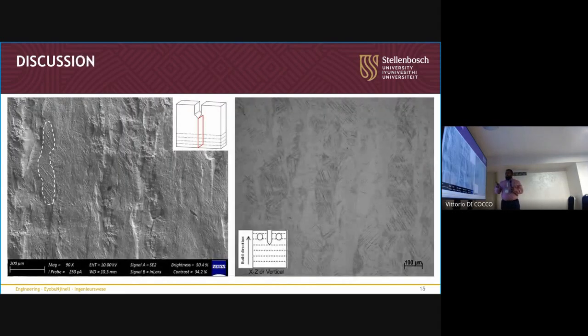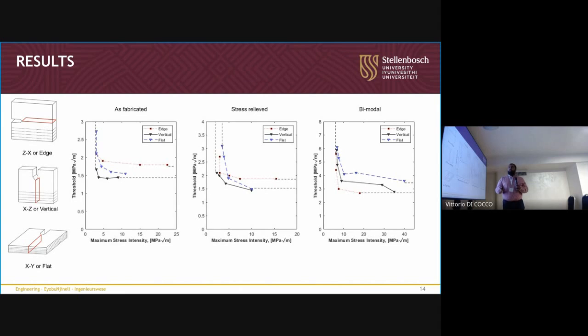The idea is that this somewhat vertical portion is more affected by the crack closure effect, so roughness, maybe plasticity, where once you get rid of that and you have higher R ratios, you don't have closure effects anymore behind the crack tip, and so it becomes what's more intrinsic to the material. It's what they call closure-affected and closure-free regions. So the mechanisms change accordingly.